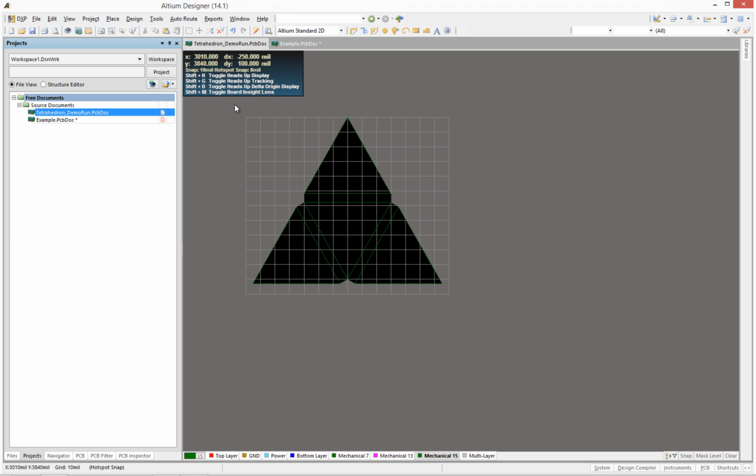If you don't do that and you have to make some changes, it gets very tricky, because Altium doesn't allow you to easily just change a section in terms of its shape, and even changing a line over here can result in it basically saying, I don't know how to define this section, redefine it for me. So just be aware of that. But for now, it's all defined.